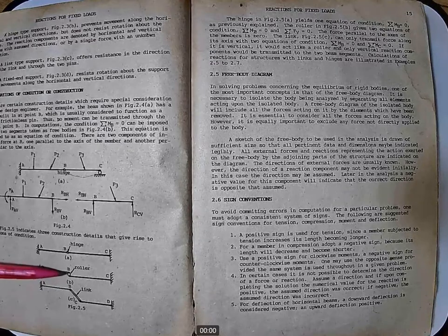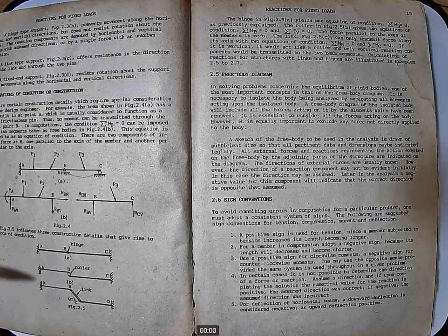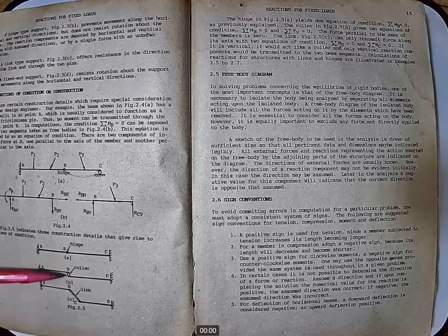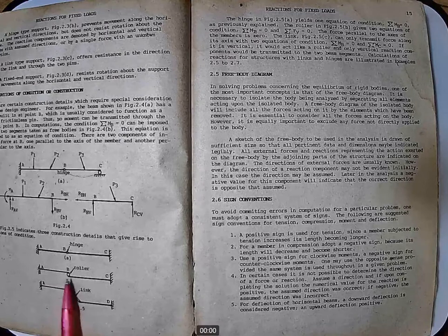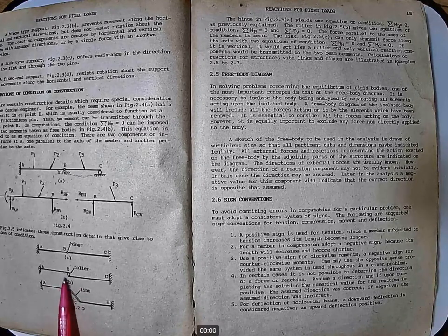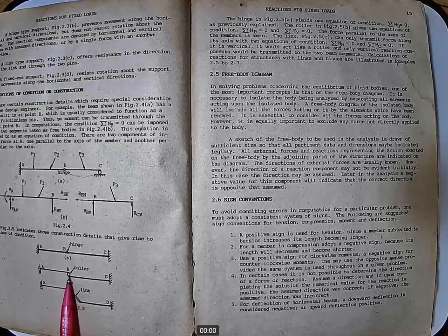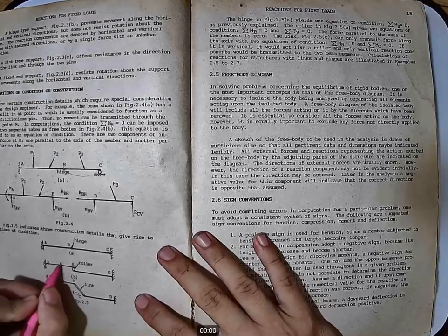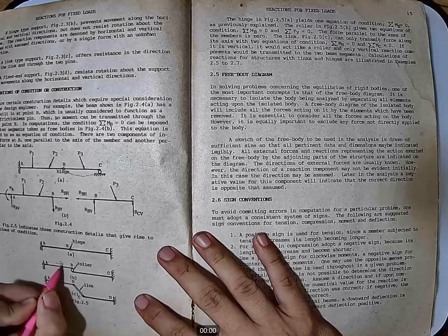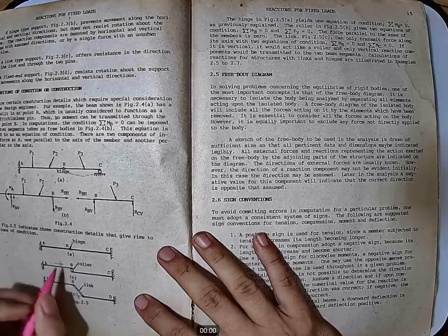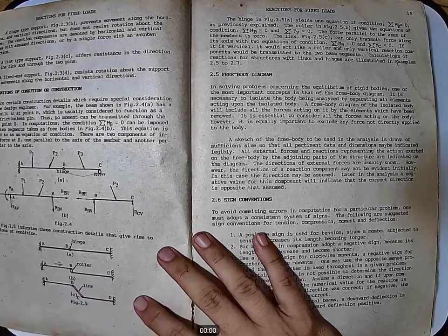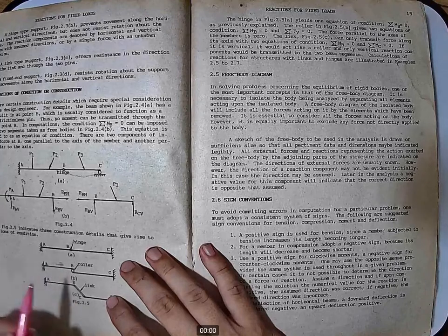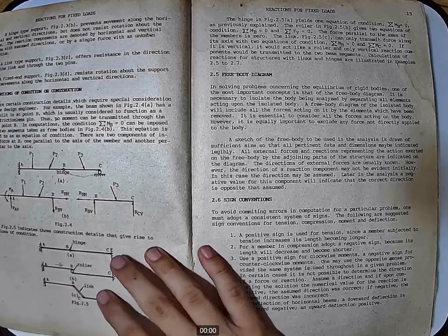Now let's go to this point. Obviously, summation forces vertical here at point B is also 0. But, it is a roller. So, the equation of summation forces horizontal does not apply. For example, along AB, you put a horizontal force. You might think that horizontal force will be transmitted here. It will not be transmitted. So, summation forces horizontal does not apply to your roller support.